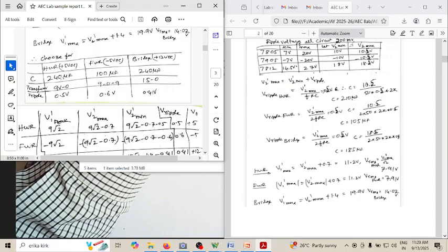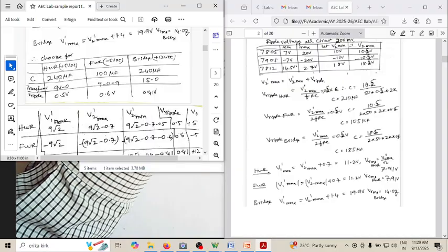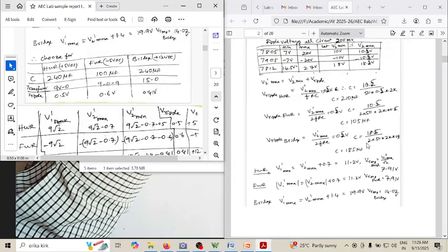I think we have 220, so you use a 220 microfarad, which is a standard one. Here you can see you have 105 as a design value, but what is actually available is 100, so you can use 100. Again, 185 is not a standard value, so you go for 220.